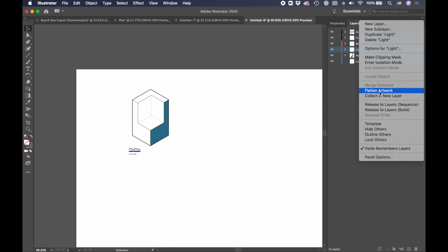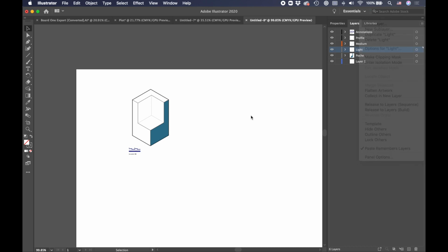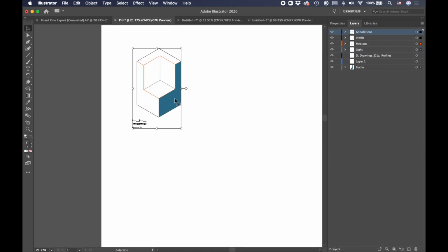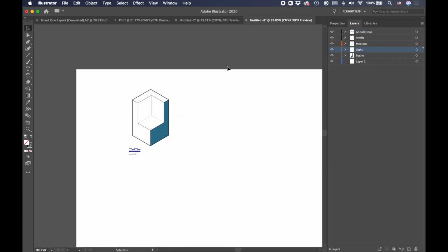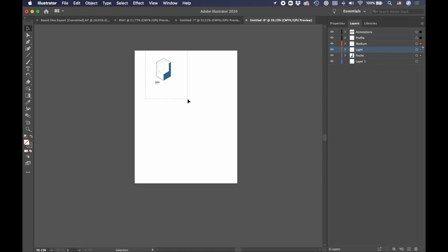The other thing is there is an option to scale your line weights as you resize them, like using this dragger. I actually do not recommend you do that, only because it will scale too small when you try to scale it down for something like a portfolio. In the same way that you're optimizing for your boards, you will eventually have to optimize for a page on your portfolio. And this is where having individual files that you can copy over to an 8.5 by 11 document that represents a page in your portfolio will help tremendously.